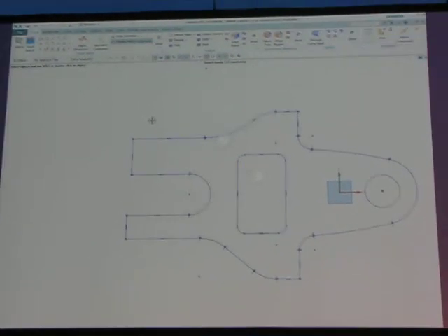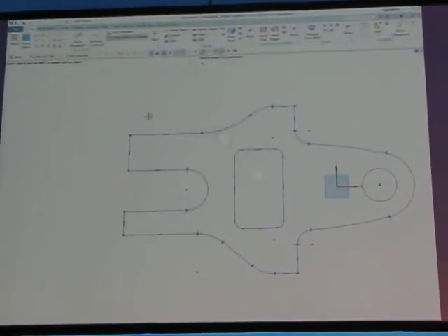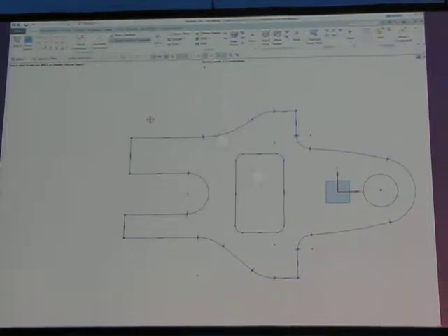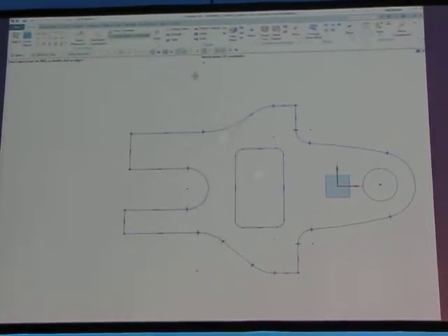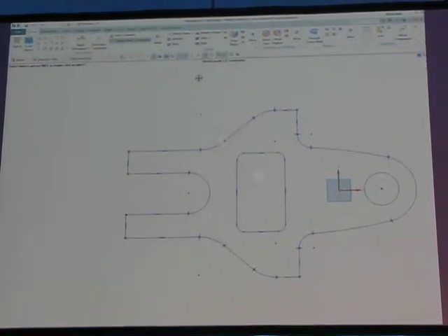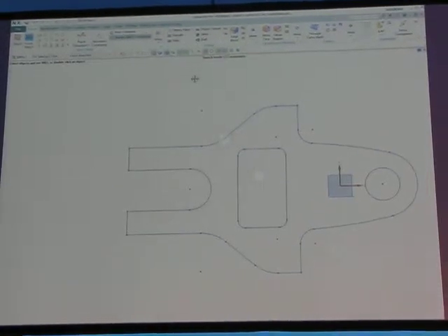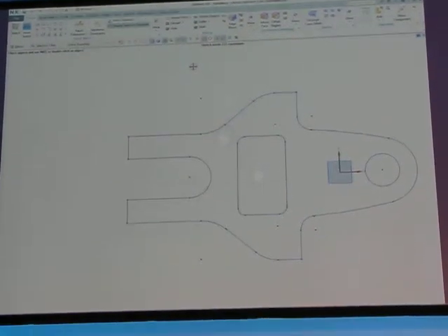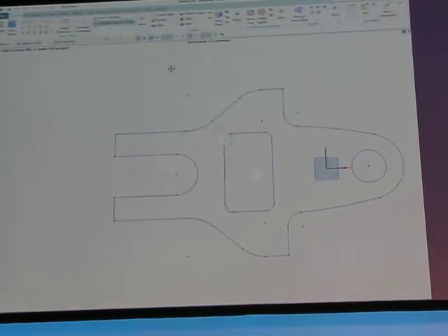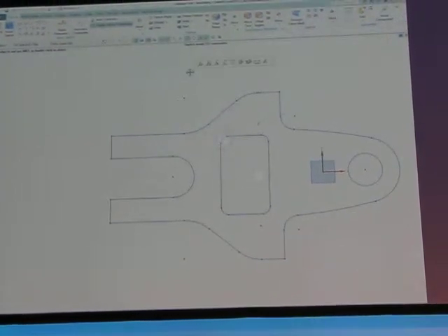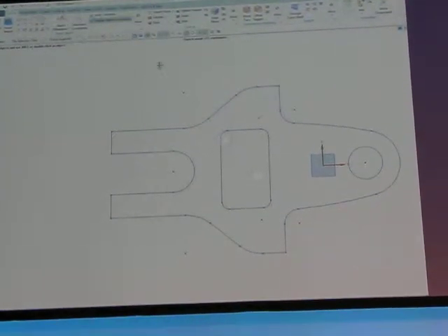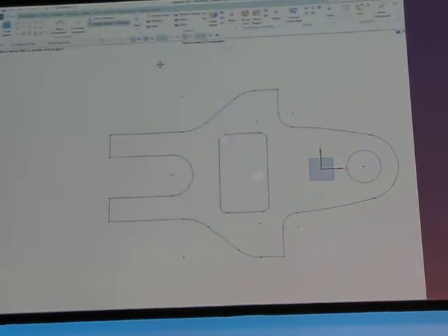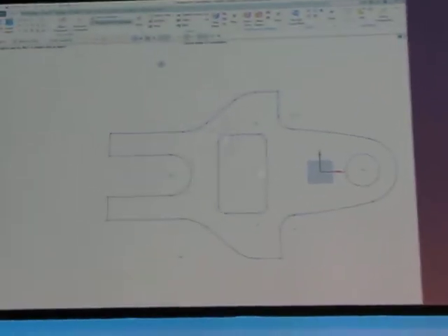All right, so here's the question. What's happened to the big radius? It changed size. How do you stop it from changing size? Constraint. You add more constraints. You fix it, you add dimensions, you add more information. So that was the problem. And yes, we gave you auto dimension, but the problem is that you have to give lots of information.